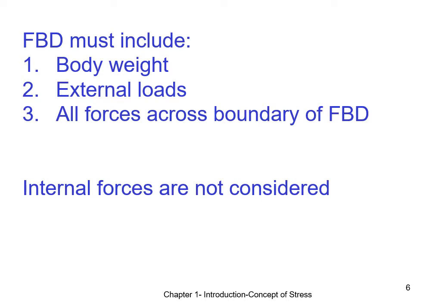In this course, we will need to draw a lot of free body diagrams. A free body diagram is an illustration of how different forces act on the object of interest. The forces to consider are the body weight, external loads, and all forces across the boundary of the free body diagram. Internal forces are not considered. We'll take a look at this further.